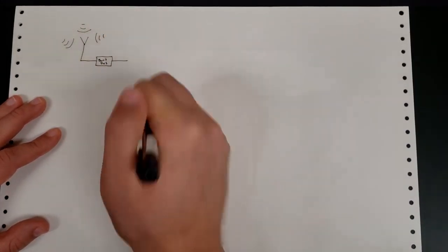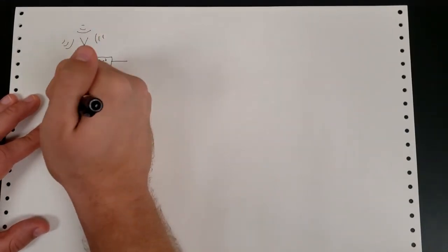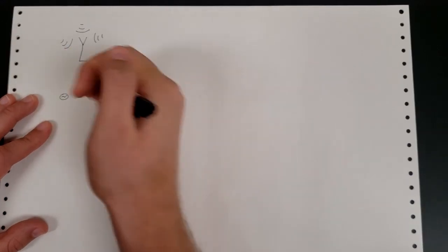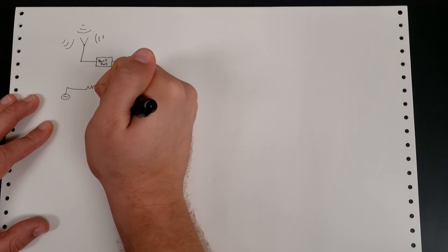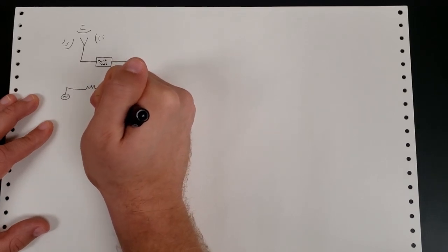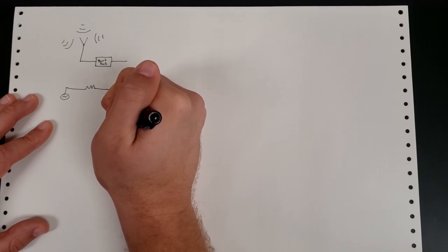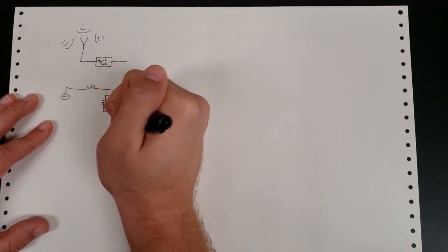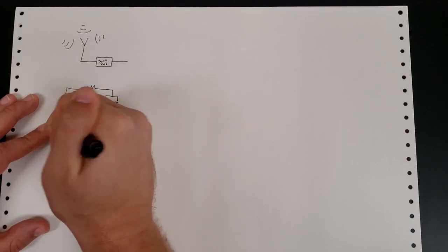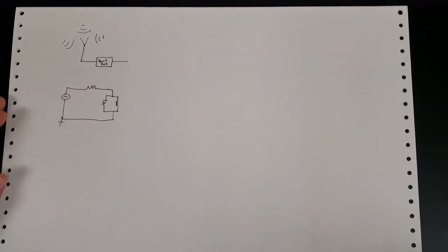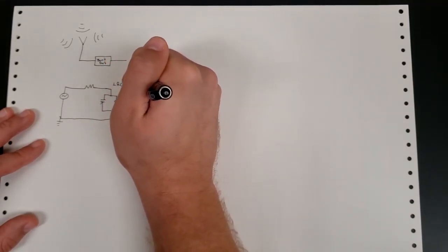This is something that we've talked about before, but just to give you a really brief overview of what this looks like. We have our alternating signal, we have our resistor, and then bandpass means that the capacitor and our inductor, which is also our antenna, are going to be in parallel. And then we have some ground over here. So this is our LRC bandpass filter.